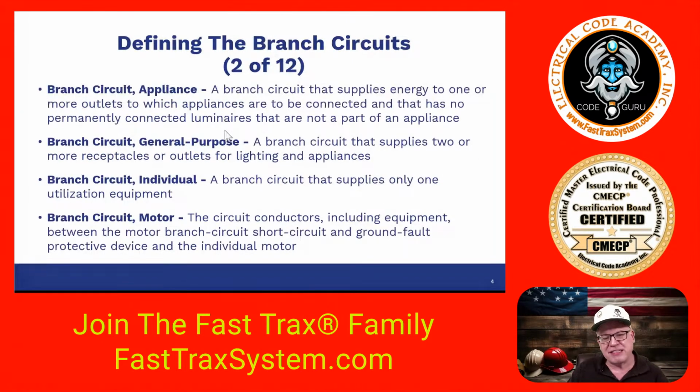Now, there are different types of branch circuits that we need to be aware of. Whether you're in residential or in commercial, you're going to hear people talk about appliance branch circuits, general purpose branch circuits. What is an individual branch circuit? And of course, in commercial and industrial, we have a lot of what's called motor branch circuits that we have to be aware of. All of these branch circuits, again, have something in common. From the last overcurrent protective device out to the outlet, those conductors are branch circuit conductors. So let's look at each one of them.